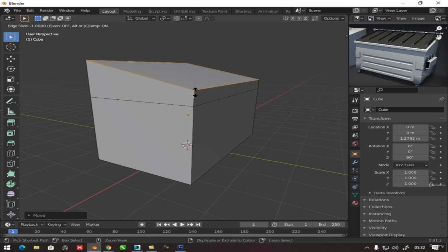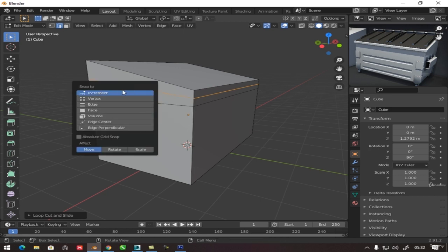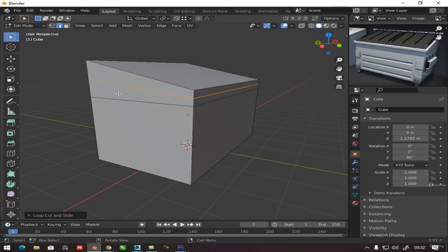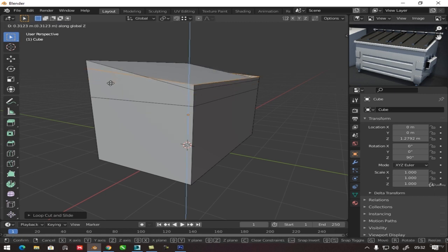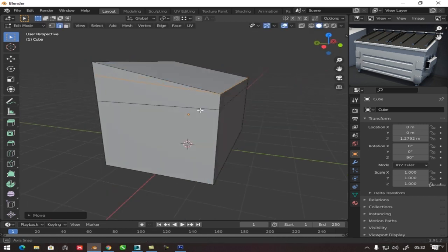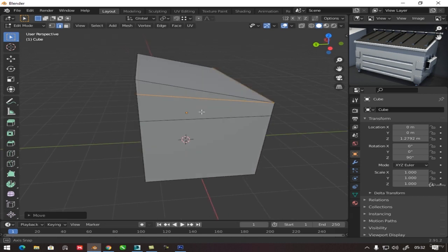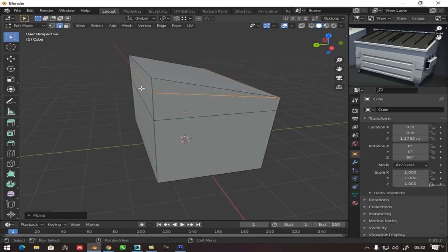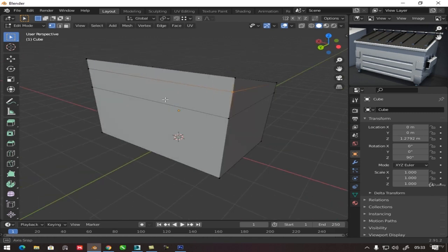To here. And here I press Ctrl R, bring it to the top. Or even to here, more or less. And I'll press Ctrl Shift Tab, and it will open a panel of snaps that floats, and I can click in vertex, G, Z, go to the top. With the Ctrl press, I can click on the top of these vertices. It will do the snap of the vertices correctly.